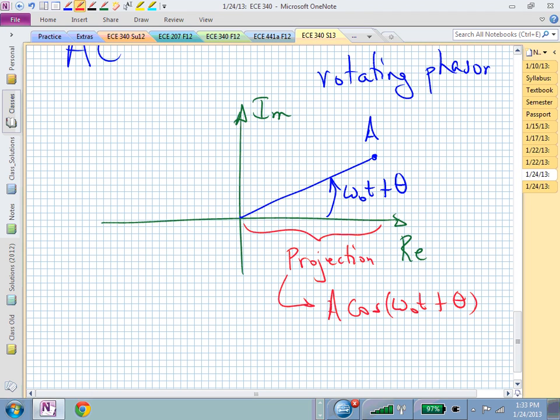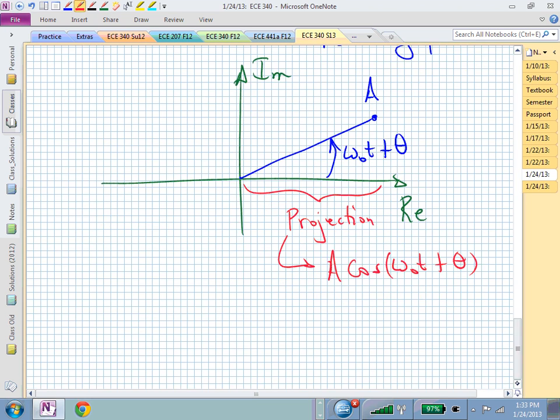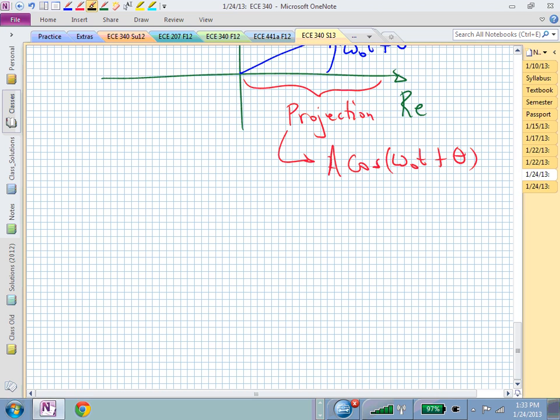Now, we can actually capture this information other than just this complex S-plane. We can capture this in a line spectra. What do we need to capture? It'd be nice to know the magnitude, the amplitude. It would be nice to know this angle, and it would be nice to know omega naught. Well, our line spectra allows us to do that with just two plots, so it's sort of like the Bode plot. We're looking at magnitude and angle information. And this will be called, like I said in Chapter 6, we'll be playing more with this, but you can now understand what's going on with this single-sided line spectra.